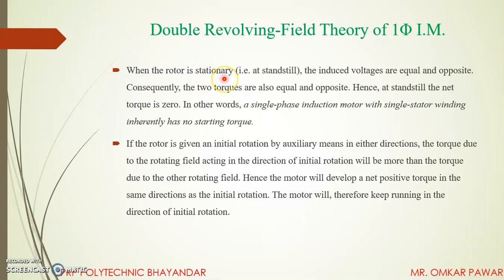So when the rotor is stationary, that is at standstill, the induced voltages are equal and opposite. Consequently, the two torques are also equal and opposite. Hence, at standstill, the net torque is zero. In other words, a single phase induction motor with a single stator winding inherently has no starting torque.